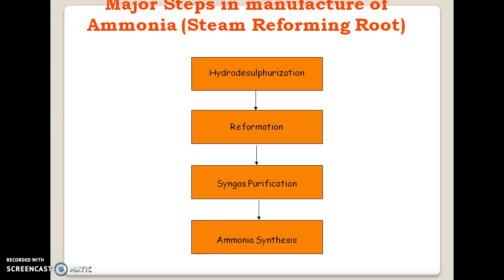Now we have to make sure there are no contaminants which can deactivate the catalyst. So can you please think for 10 seconds what would be a deactivating contaminant? Yes, so what would it be? Sulfur in the form of SO2, correct? Or, as in the reaction we saw, what comes out with hydrogen is carbon monoxide.